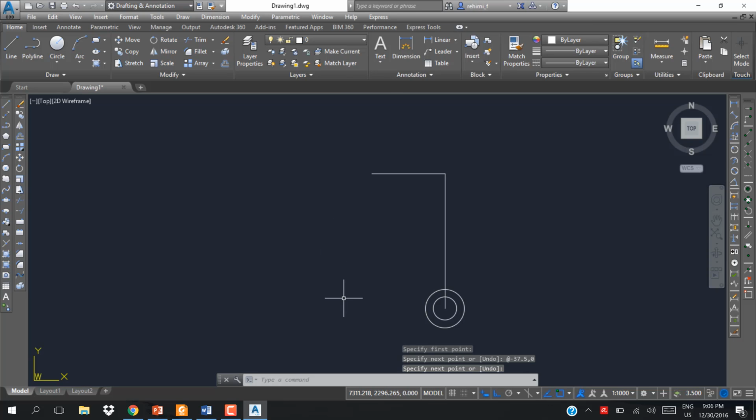So now CO for copying, or you use the copying option here, and I copy. You select the objects, this one, by the left button, and you confirm by the right button. Now they are asking you for the displacement. So you take from this node or from this point to this point, space or enter. Now you have drawn your circles on the right side.